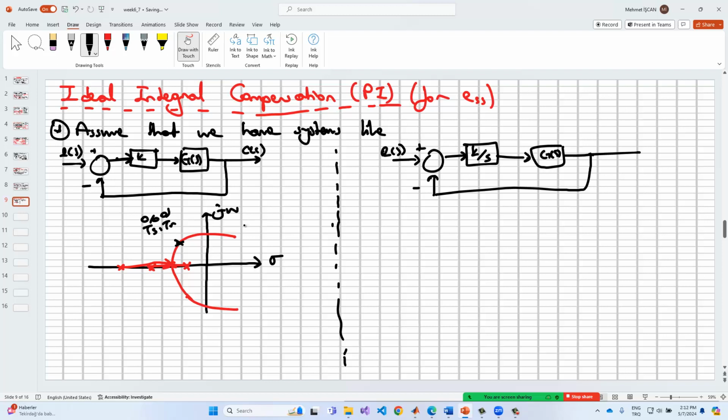But maybe we need to add another pole in here in order to adjust the new root locus, because if we have the root in here, just like this one, for example, this is the -2 plus 5j, and so this suppresses the whole integral or the steady state error, but we cannot reach it because the selected K cannot compensate all of these things in here.